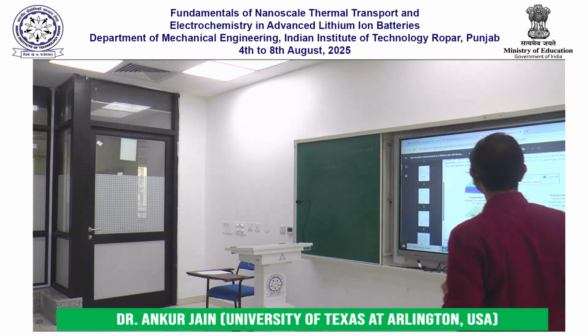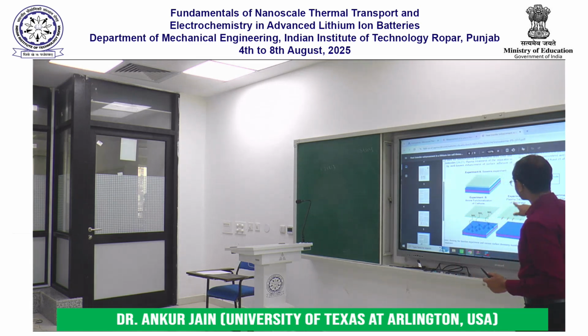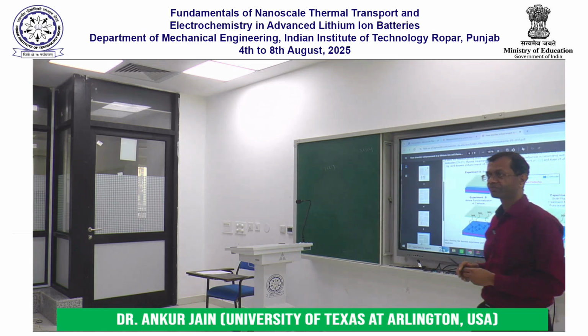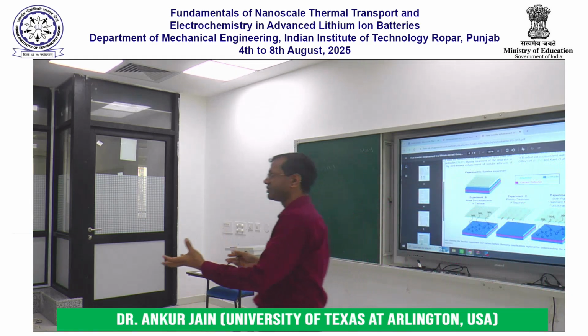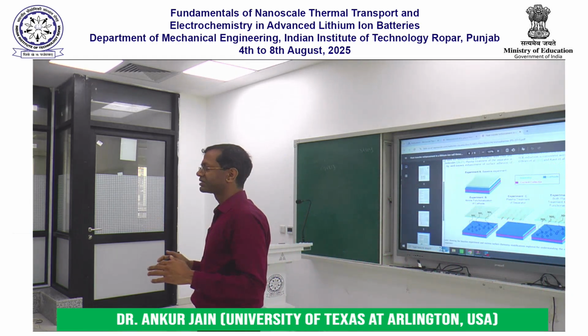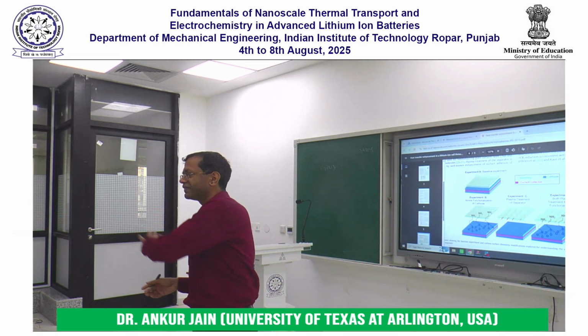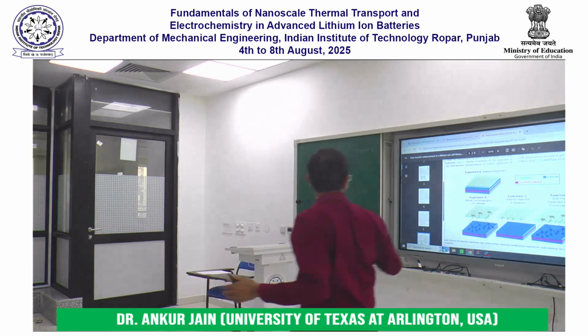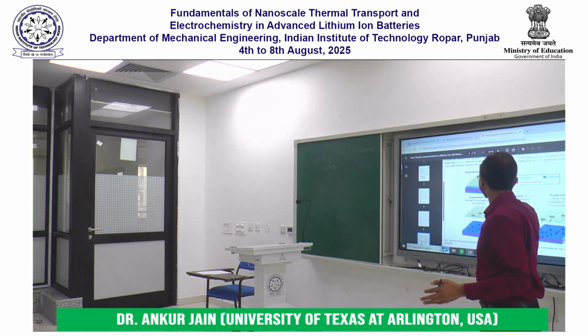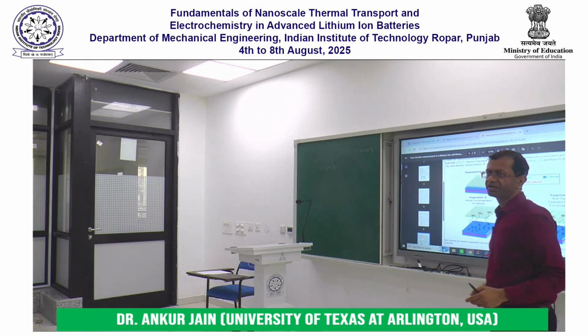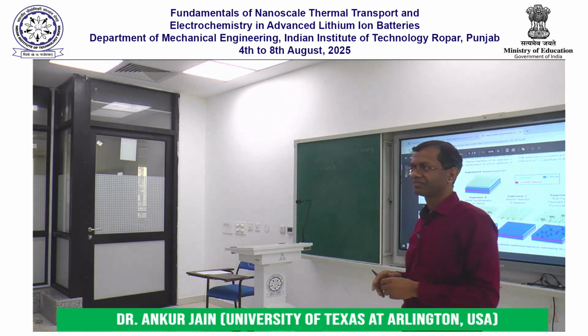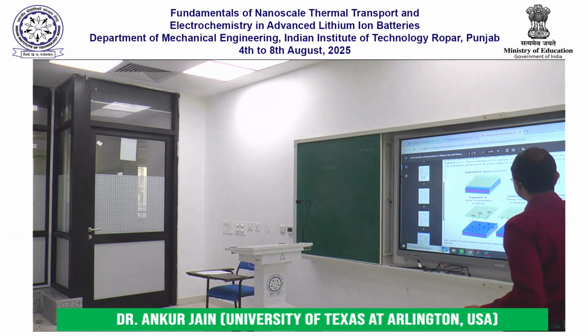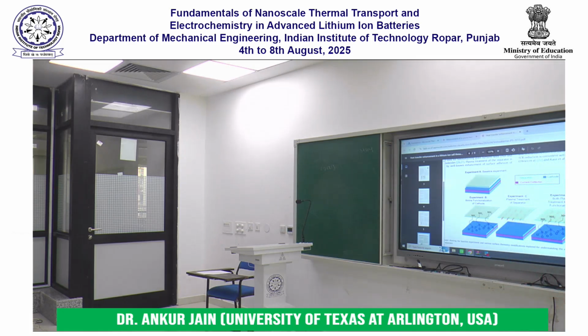On the other side, we carried out a plasma treatment of the separator. So just stick it in a plasma, oxygen plasma for 5 minutes. That basically cleans up the surface and provides a slight positive or negative, I forget what, charge on that surface, right? And then we stick them together. So experiment A is the baseline.